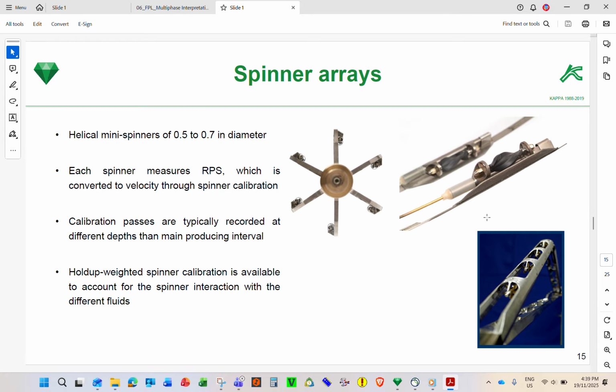As for the mini spinner, so this is the set. You can see the set is something like this. So you have some dots, which are the magnets, and you have a Hall effect switch here. So when the magnet passes through, it switches on, off, on, off, on, off. So the number of rotations will be the number of signals. So you will be calculating the signals as CPS to get the RPS, depending on the number of magnets. It's only one sensor.